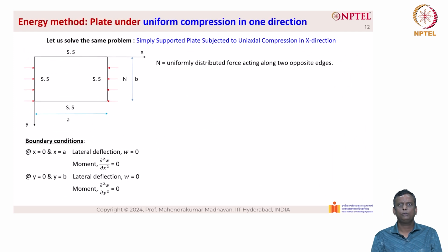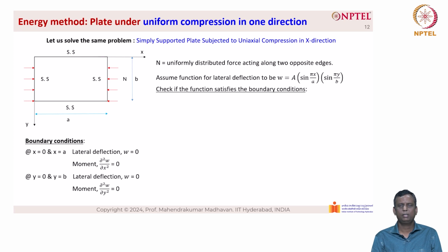Now, where N is the uniformly distributed force acting along the two opposite edges, let us assume a lateral function w, which is also known as the deflection function, given as A into sin(πx/a) into sin(πy/b). The first important thing is to check if the function satisfies the boundary conditions.